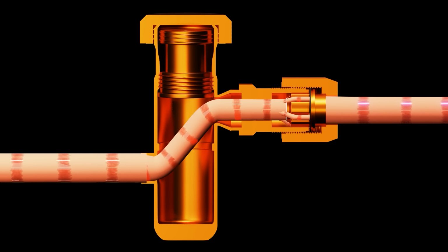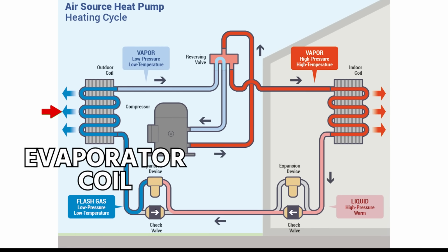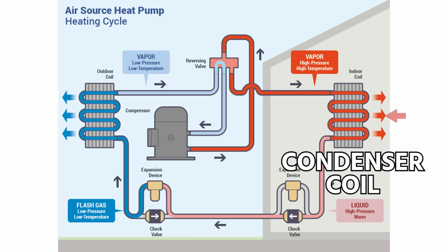But then when the flows go the opposite direction, it seats the piston, and that forces refrigerant through it, which then makes the outside coil the evaporator coil rather than the condenser coil. So that acts as an outdoor metering device.